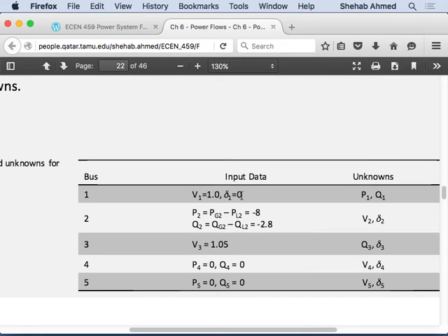If it converges, use the numbers that you have at the specific buses. Because remember, we have PK and QK equations at every single bus, so you have to get estimates of all the voltages and angles in your system to be able to start. So you initially said, okay, I will have all voltages as 1 and all angles as 0, and it did not converge when the load is very high. But when you decrease the load, it converges. So how about increasing the load slowly, and every time keep increasing until it stops converging. When it stops converging, decrease it a little bit, and take the numbers from the previous step where it converged and use them as your start.